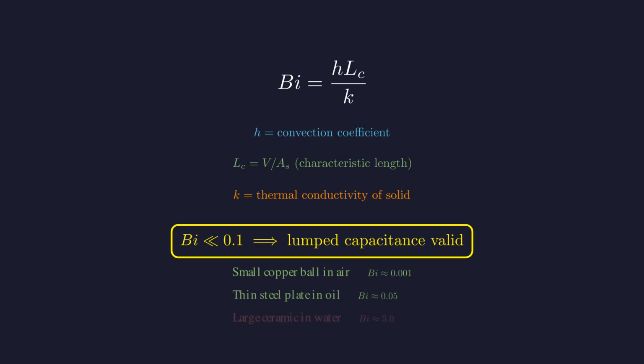Think of it this way: if the solid conducts heat easily, it equilibrates internally much faster than heat leaves the surface. Small copper ball in air, perfect. Large ceramic block in water, not valid.